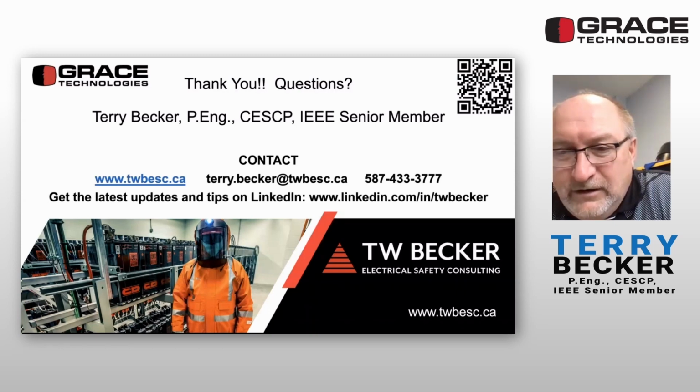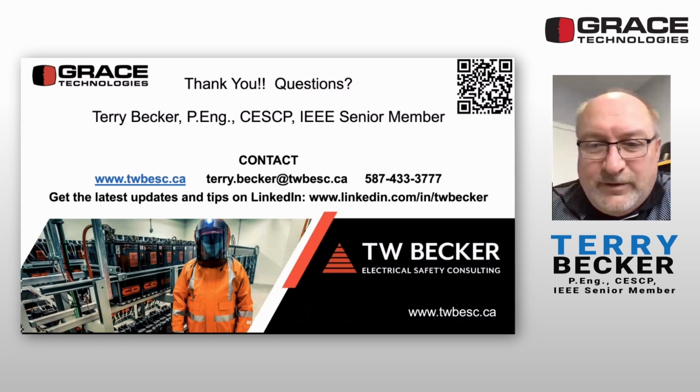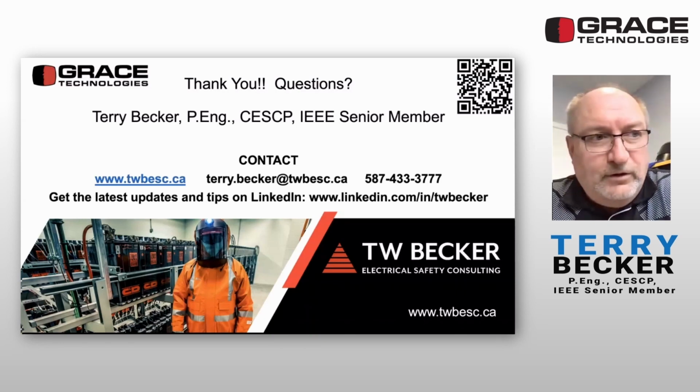Wouldn't that technically mean you'd need to wear PPE walking in front of the panel if the depth of the panel was shallower than the safety? No. Well, this is the other problem. An abnormal arcing fault likelihood is no for normally operating electrical equipment. So we don't need arc flash PPE or shock PPE to walk in front of any enclosed electrical equipment, low or high voltage. You never did, because operating the electrical equipment doesn't have a likelihood of creating an abnormal arcing fault while you're standing in front of it. And again, that's another debatable issue, but it's true.